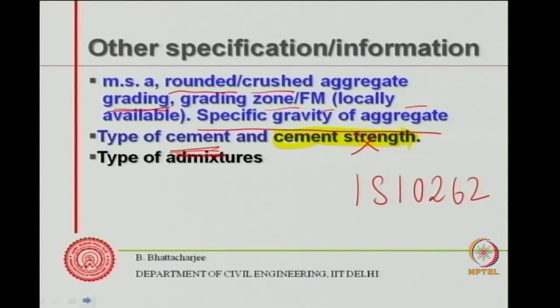If I am using some admixtures, what is the kind of admixtures I am using? That information is important, and its compatibility with the cement and the other system, the overall system, that is also an important aspect.